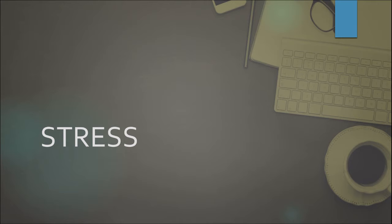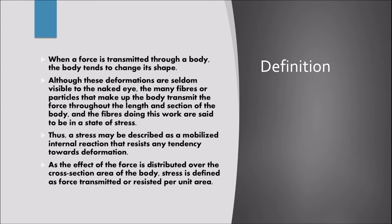So what is stress? It is when a force is transmitted through a body, the body tends to change its shape. Although these deformations are seldom visible to the naked eye, the many fibers or particles that make up the body transmit the force throughout the length and the section of the body, and the fibers doing this work are said to be in the state of stress. Thus, a stress may be described as a mobilized internal reaction that resists any tendency towards deformation.